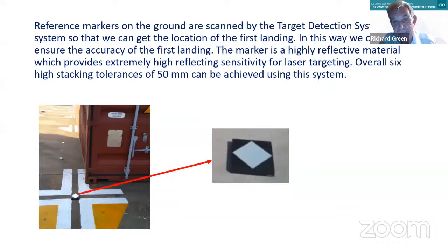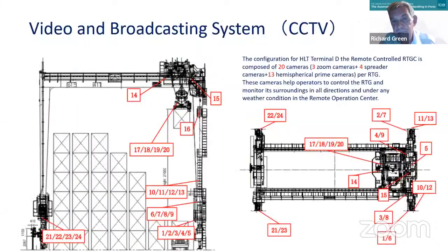If you're using this type of system, you need to be acutely aware that you cannot tolerate differential settlement. So you need to make sure that when you're doing the construction work, all the preloading and everything is done properly. Video and broadcasting system, CCTV.